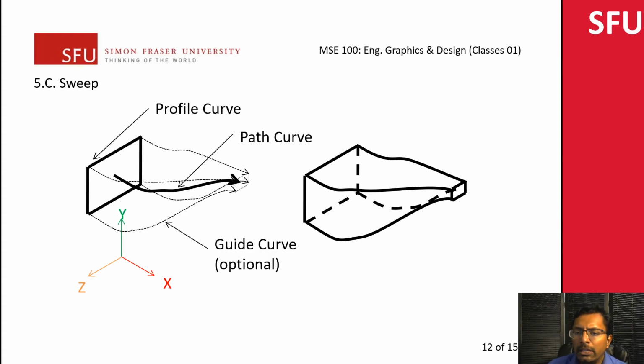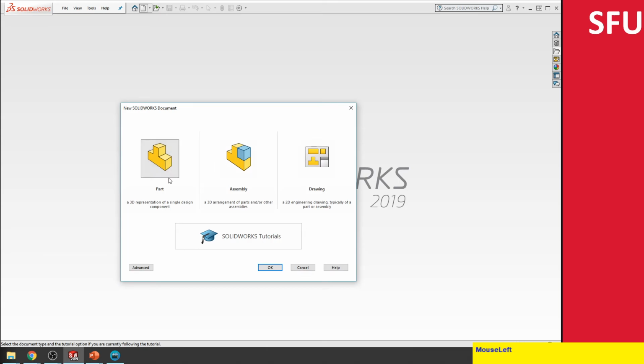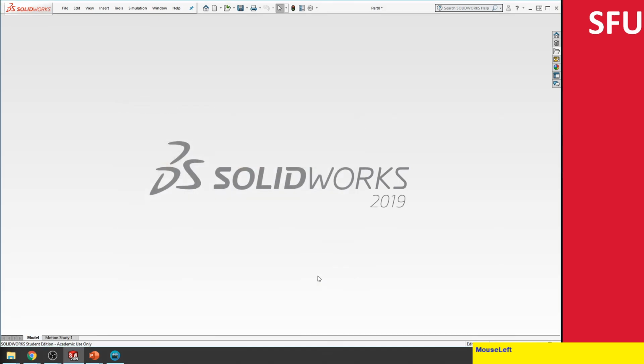In order to get the profile to work, we're going to use something known as a pierce constraint. The profile doesn't work without actually using the pierce constraint. So let's see how that actually works. Switching to SolidWorks over here. I closed all of the windows in the meantime. So let's do new, click on this.